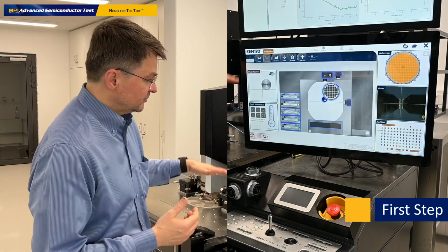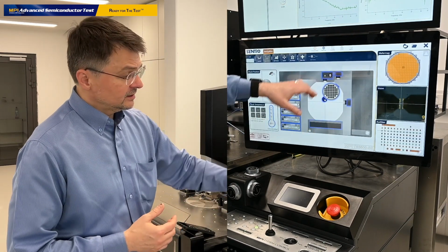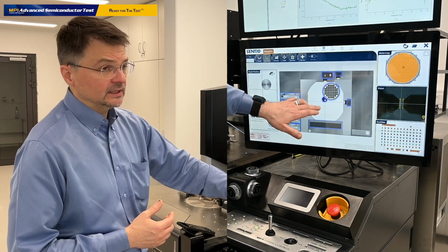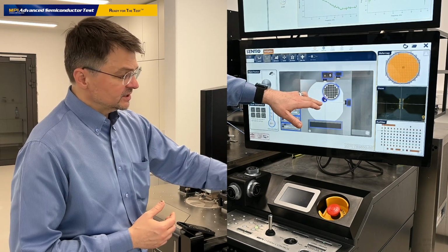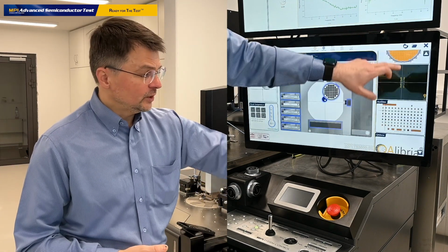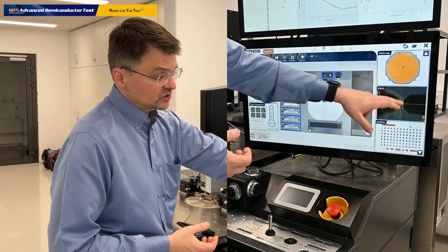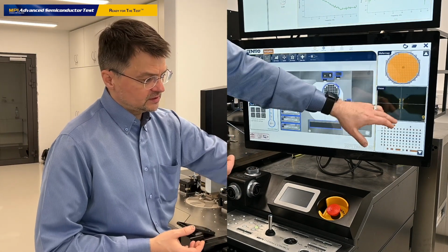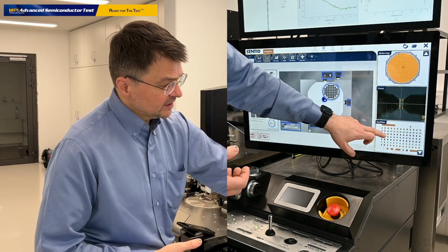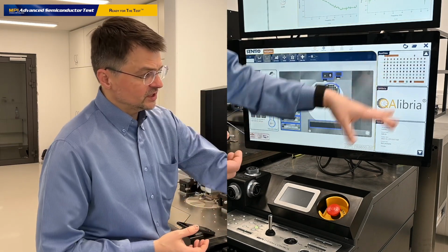So in Sentio, what you can see from the screen is a dashboard which shows us the current status of the system. What we can read from the dashboard is that the chuck is currently located under the scope, and this is our auxiliary chuck where we have our calibration substrate. On the right hand side we have a set of tools. The carousel menu for different tools is wafer map. Then we have a vision system where we observe our probes, and we see that we are currently over the load standard. Then we have an auxiliary side management module which helps us to navigate across the calibration substrate.